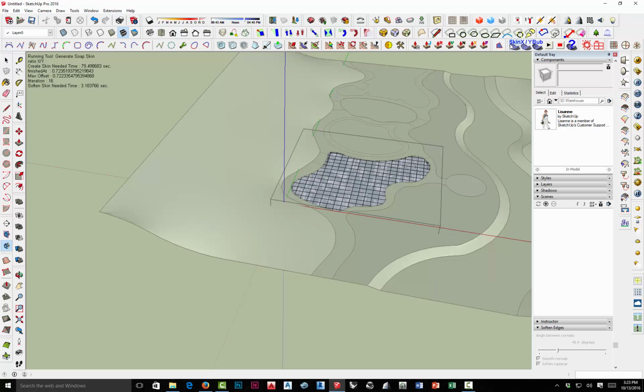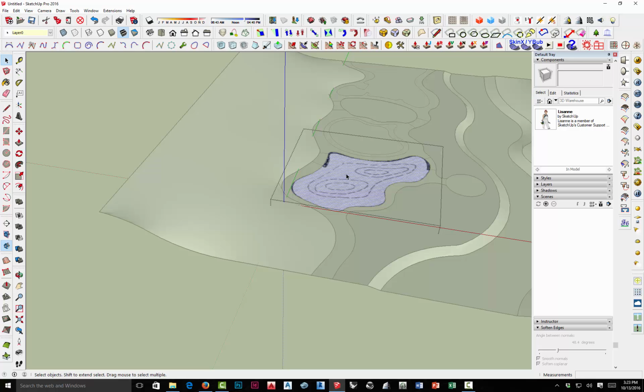And I'm not going to go into it here, but part of the artisan tools allow you to subdivide an area and actually create a finer grid within a larger grid. So where you need detail, it's called mesh subdivision. It's actually one of the methods that's more popular now than even polygons or NURBS modeling because you only add the detail where you need it, and where you don't need it, you allow it to be simple. All right, select, cut, click, delete, paste in place, then explode.